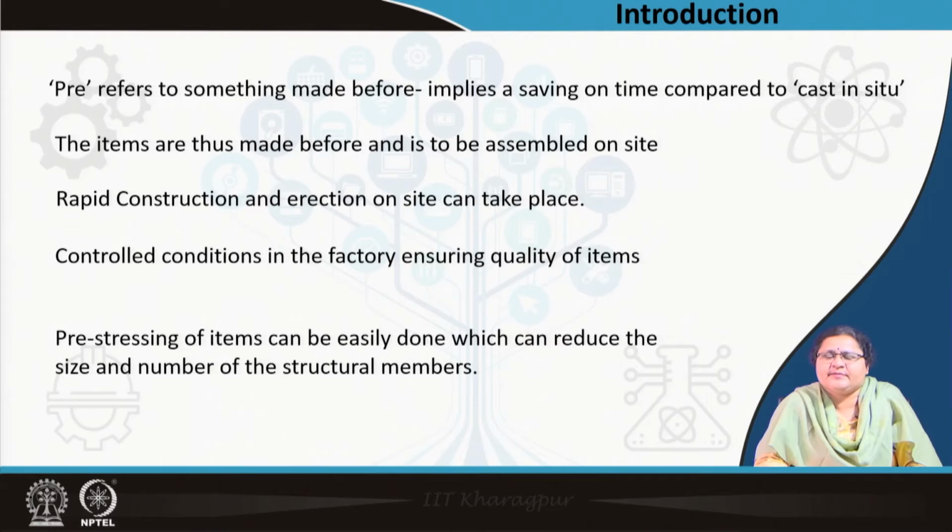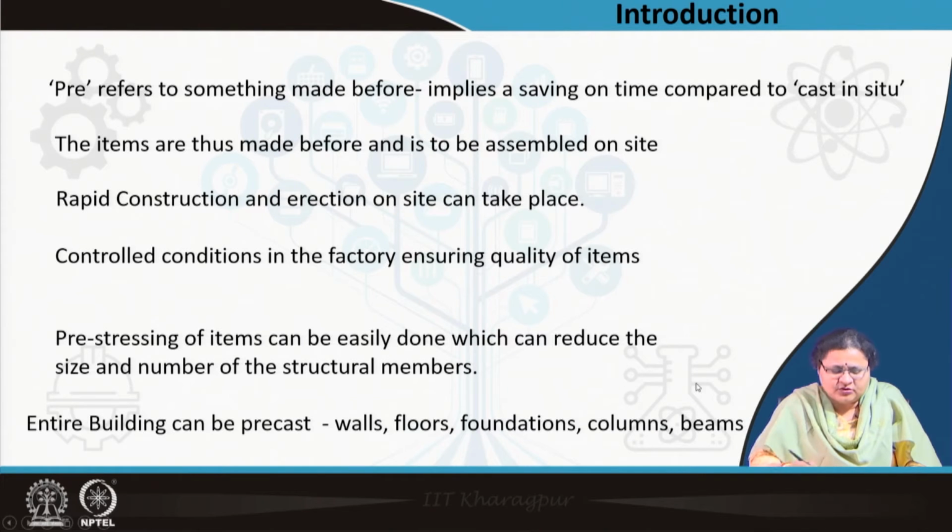Pre-stressed items can be made in factory. What is pre-stressed? Means the rods or the reinforcement, that is the steel bars which are inside the structure, as these are quite long structures or large structures, concrete is good in compression, you have to use steel to take the tension. So, these steel rods can be pre-stressed and can be embedded in the concrete.